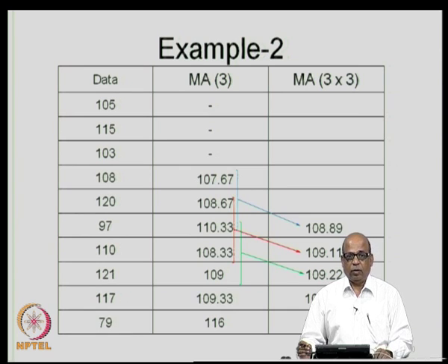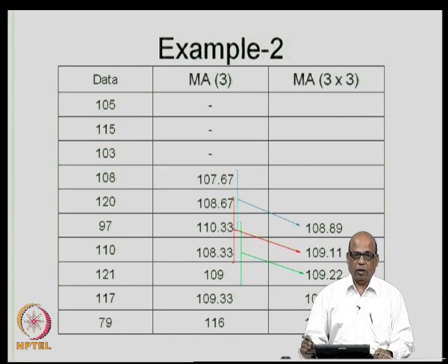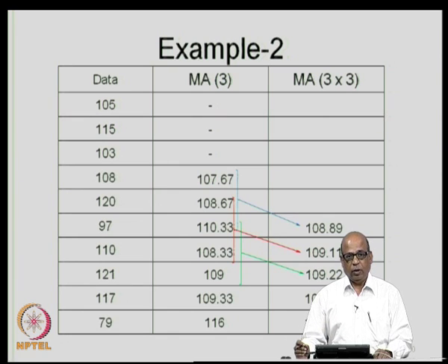If you have data on monthly stream flows, for example, this kind of methods may not work well, because monthly stream flows exhibit a significant periodicity, especially in monsoon climates like ours, where June month flow is serially correlated with May month flow or the June month of the previous year and so on. So, there may be significant periodicities in the data. When you have significant periodicities or any significant deterministic components other than the mean, then these methods will not work well.